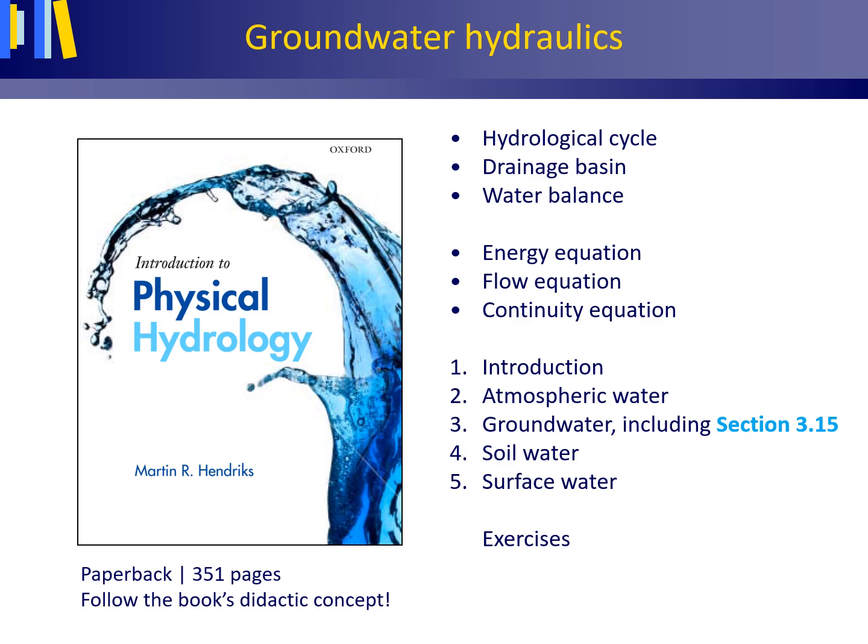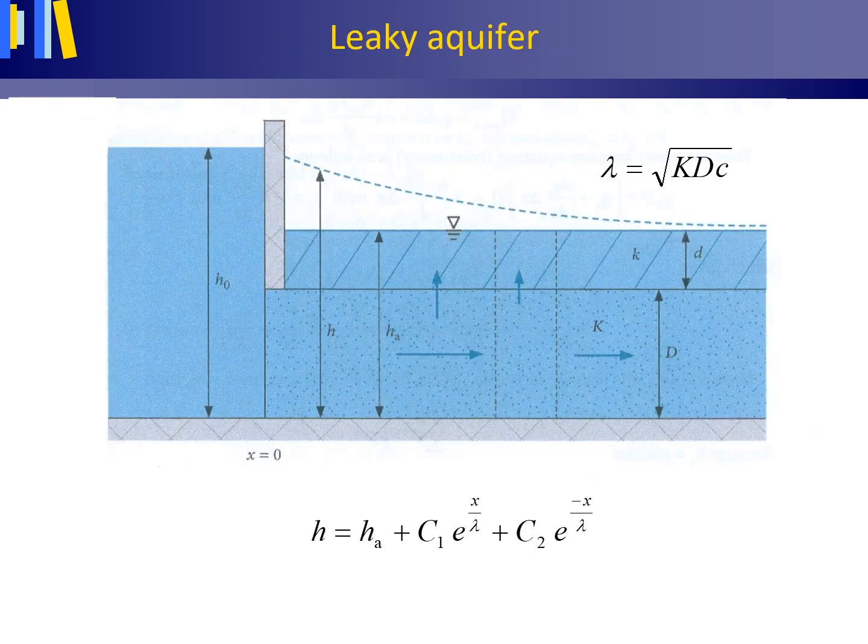For the following case, steady groundwater flow in a leaky, homogeneous isotropic aquifer, we will also deal with seepage, steady groundwater flow through an overlying leaky confining or semi-permeable layer, thus steady groundwater flow in the Z direction. This figure shows Het Hollands Profiel, a cross-section profile for the Dutch provinces of Holland, which is a special case or example of steady groundwater flow in a leaky aquifer.